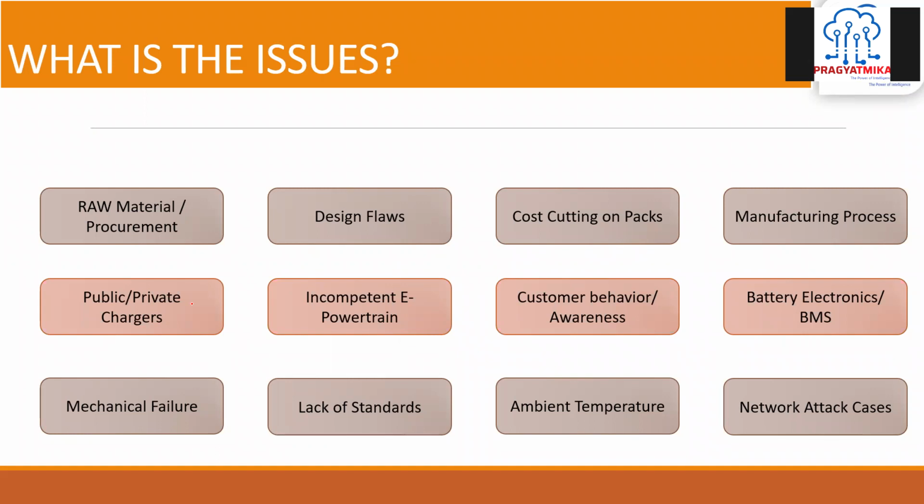The powertrain which is connected with your pack also has some issues many times, as it starts drawing a higher current, and the BMS connected with your battery pack is not an actual BMS, but just a protection device. There are BMSs which are rigid devices with certain cutoff levels, like the high cutoff level, the low cutoff level, the current cutoffs.